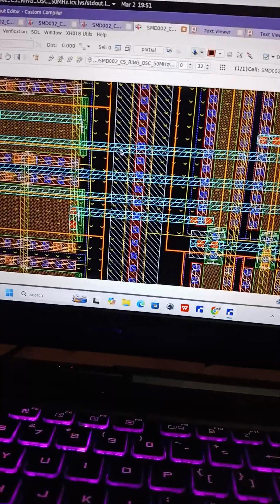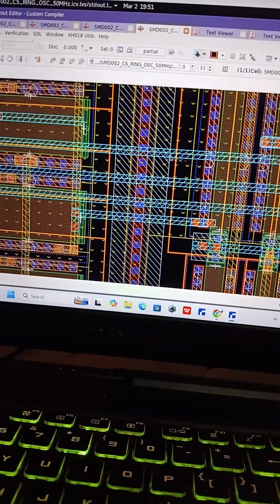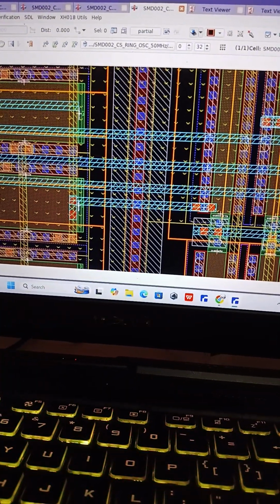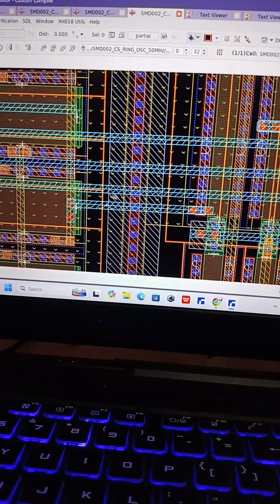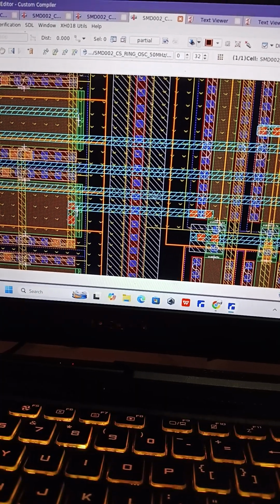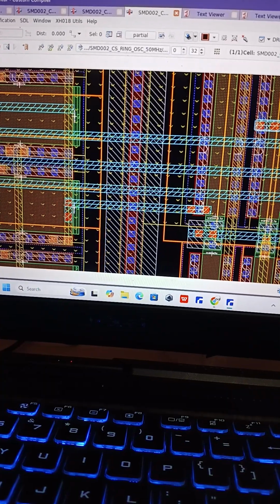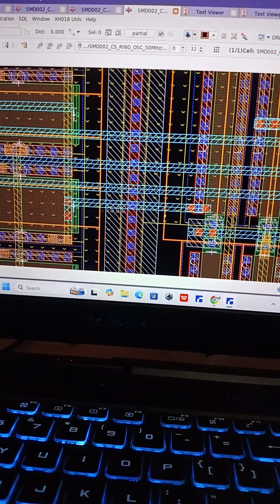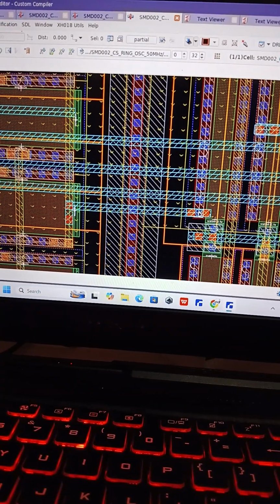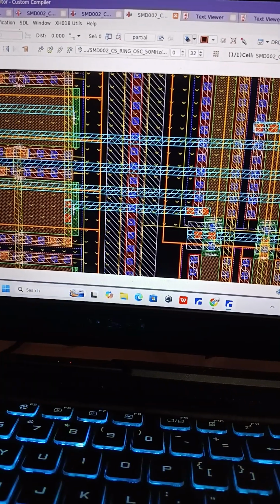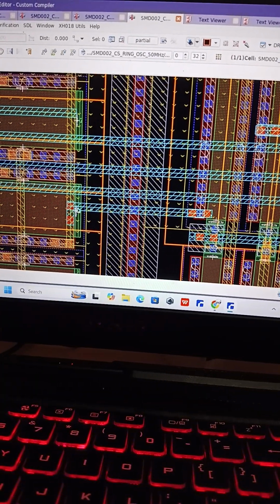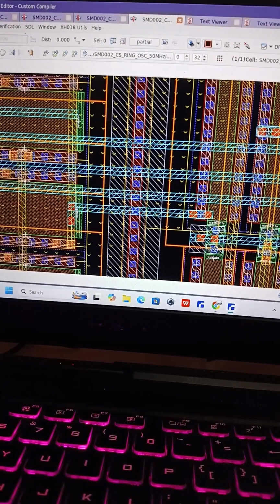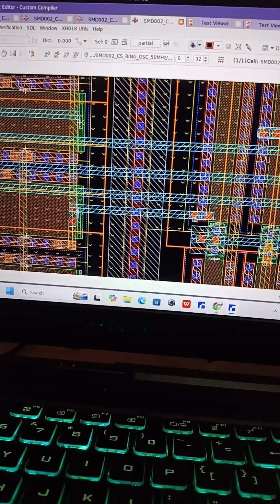So what is resistive parasitic? Let's take this simple connection, this to this. Of course current will flow, right? But because of the properties of the metal, there will be an IR drop. Let's say here is supplying 10 volt. Current flows from higher potential to lower potential. But along the way, the potential will drop.